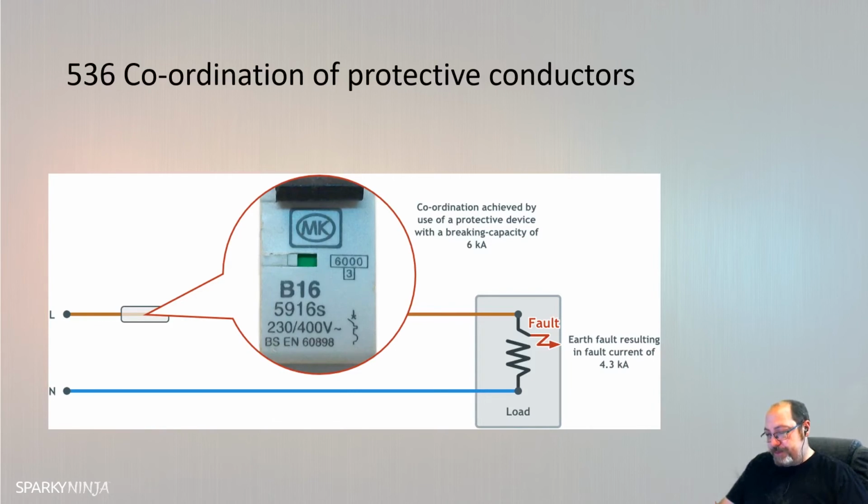Okay, so short circuit protection, we've got to consider the fact that if a short circuit was to occur, the protective device will have a tolerance for the potential value of current. So, your typical prospective fault current, your prospective short circuit current, your prospective earth fault current, the value of current must not exceed that. We have the Icn and the Ics that you'll see in the on-site guide on this. With an overload, we need to make sure that if an overload is occurring, it does not occur for long duration. Low overloads of long duration should not occur. And residual currents, we've already mentioned this: nuisance, unwanted tripping, selectivity. Okay, so that's what they're trying to achieve here.